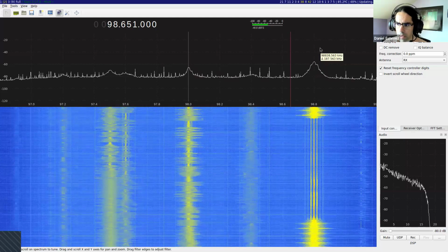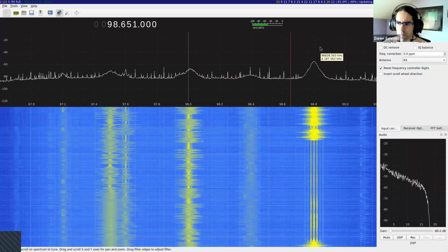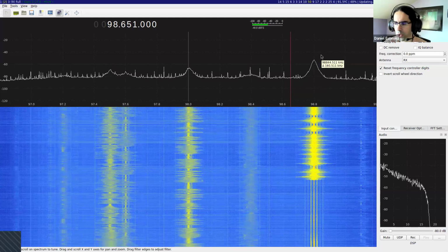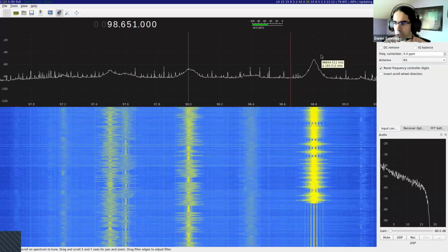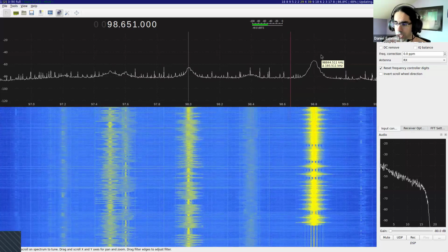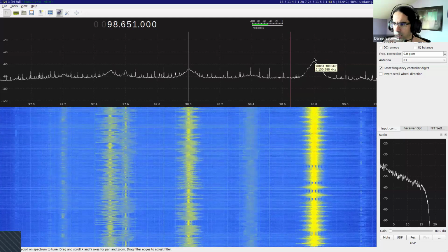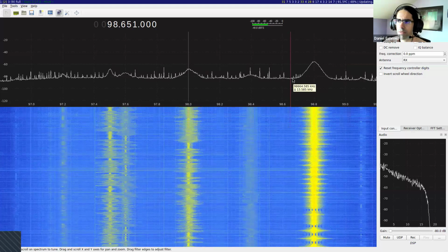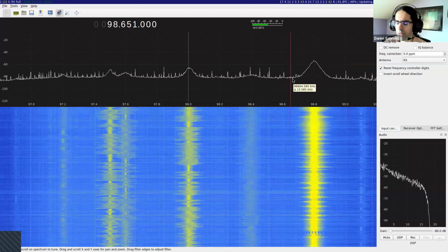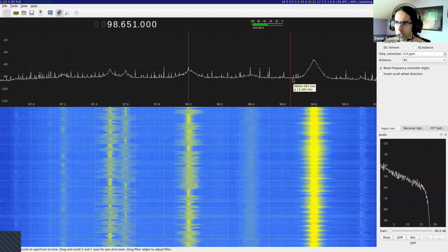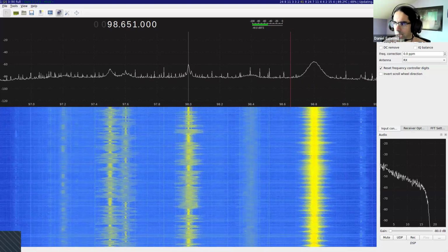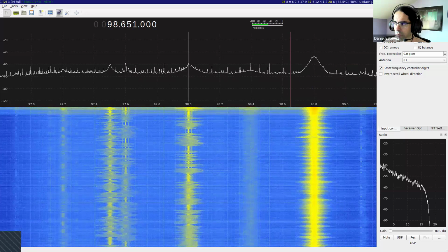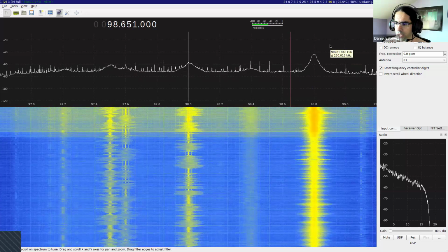There are maybe more accurate ways of measuring it, but for the time being, that's enough because we are going to do comparisons of signal to noise ratio when we change the gain. So I said here, this is minus 50, minus 85. The difference between minus 50 and minus 85 is 35. And the thing I want to do now is to increase my gain by maybe 10 decibels and see what happens.